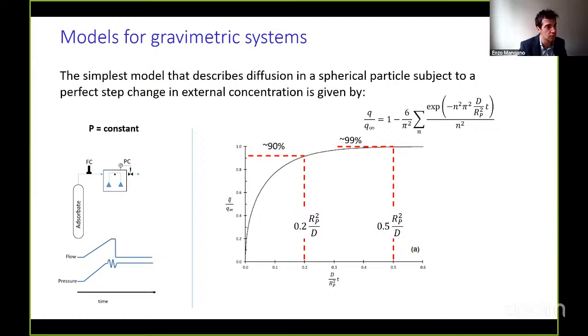And what I'm trying to explain with this is that in many cases, as I mentioned before, the transition between the application of the pressure step and what is actually seen by the adsorbent may take a few minutes. This is because of the volume of the system and the fact that you need to implement measures to prevent the instability of the balance, which require that the flow change and the pressure change inside the balance is gradual. So this transition can take up to 1 or 2 minutes.